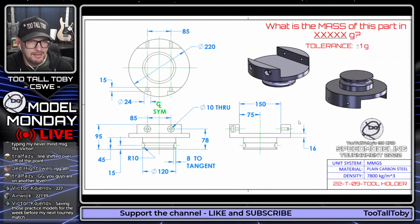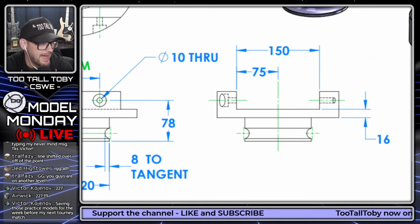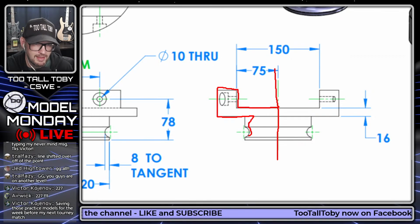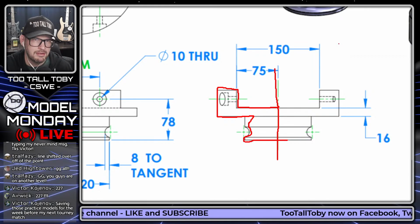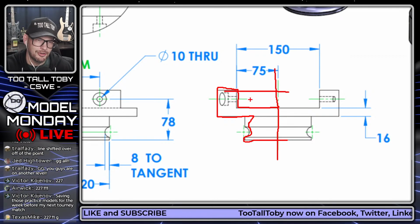On a model like this, the model is circular. You can imagine taking a cross section of the model, taking half the cross section, and then ripping that around a center line. That's what's called a revolve in 3D CAD. With a model like this, that's almost certainly what you're going to do.